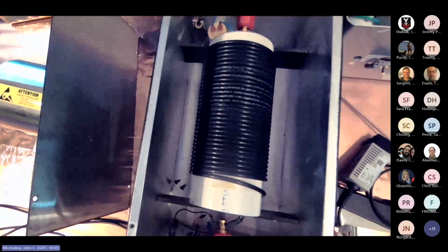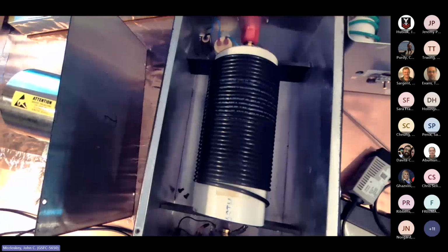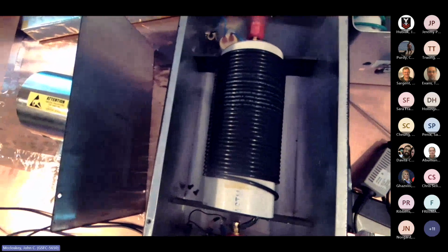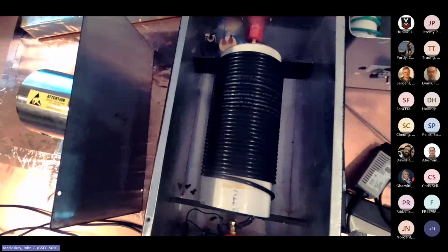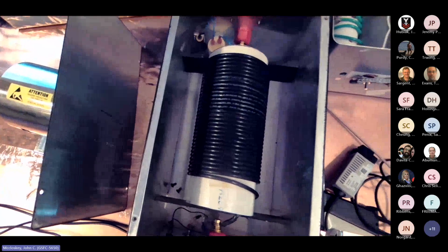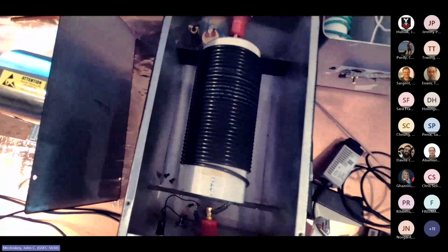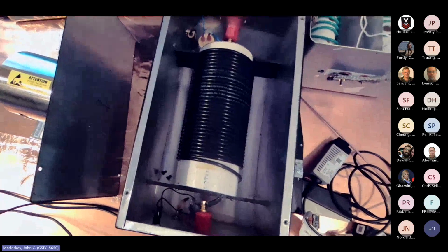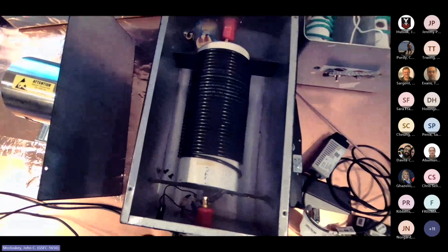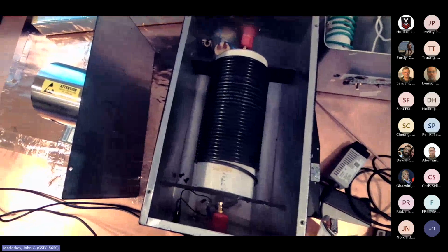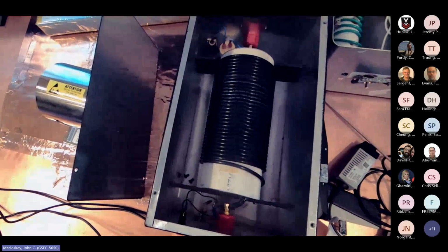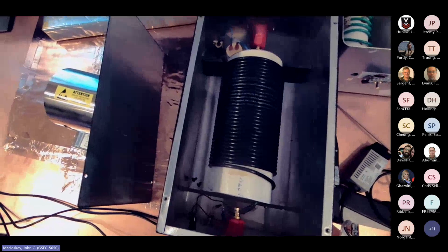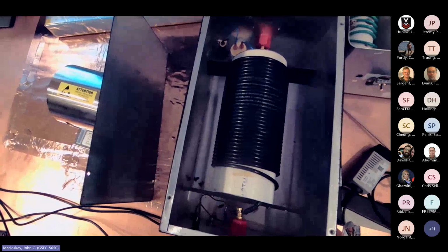That kind of configuration has an inductance per unit length of about a microhenry per meter, running for as long as 50 meters. It says that in the appendix of the Mil standard; that's where they came up with 50 microhenries as the standard inductance value to use for these LISNs. But you just see that 50 microhenries is not something you get by accident. There's no stray or parasitic inductance of 50 microhenries. You have to mean it.